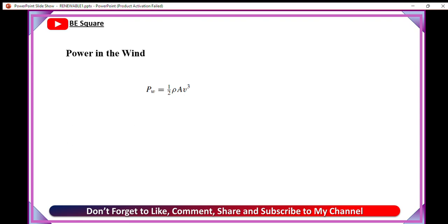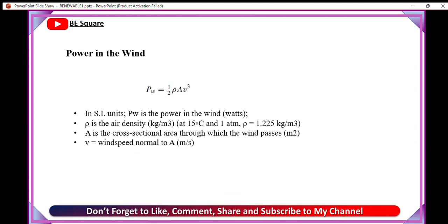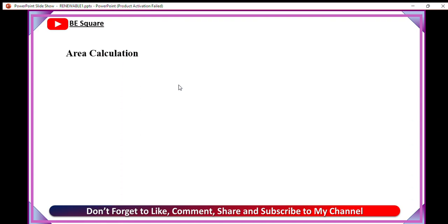Moving on to the next point, there is the power in the wind. How to calculate the power in the wind? By using the formula P_w = 1/2 rho A V^3. P_w is the power in the wind, calculated in watts, and rho is the air density, calculated at standard 15 degrees Celsius temperature and 1 atmospheric pressure, and it comes to the value 1.225 kilogram per meter cube. A is the cross-sectional area and V is the wind speed, and this power is related to the cube of the wind speed.